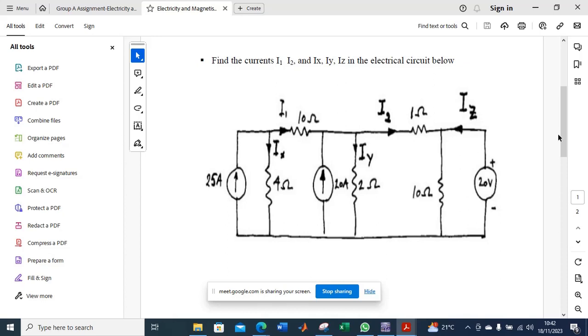For example, if it was coming from this side, on this resistor, there is always a potential drop. If you have a voltage drop, you have your positive where the current is flowing in, and after the resistor, you have a negative. Likewise, you need to put the positive of the voltmeter here and the negative on this side, so that you measure the positive value according to how the current is moving.